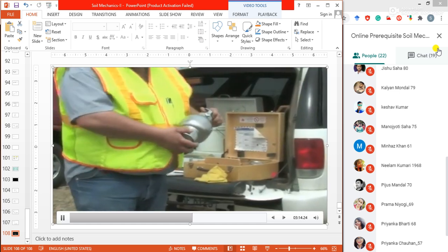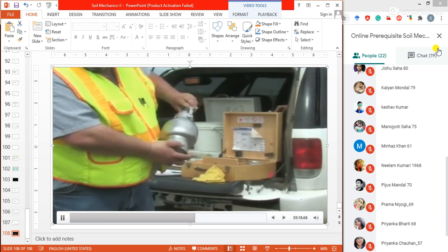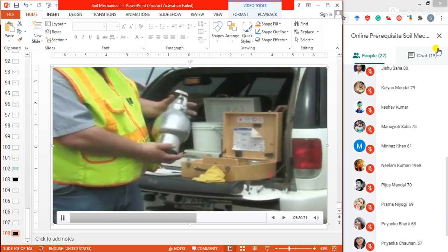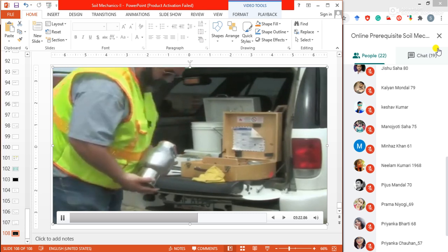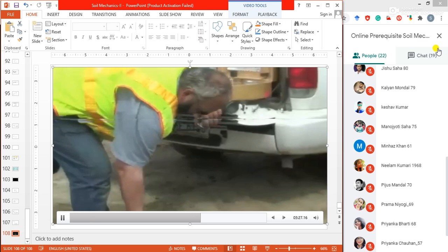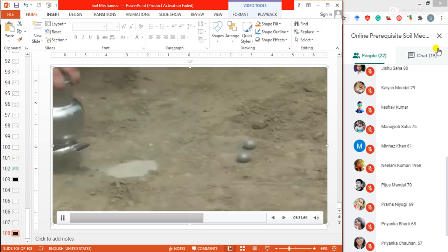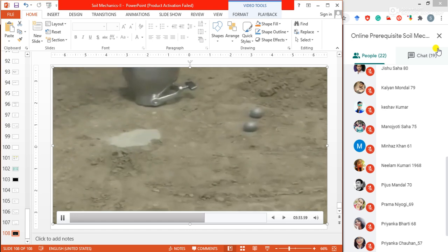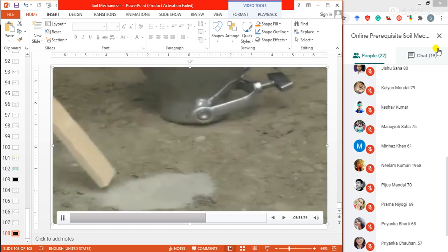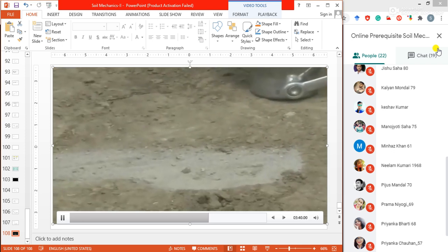At the completion of the test, the moisture tester needs to be opened carefully. Locate the arrow on the flange or lip of the cap and point this downwind and away from you. Remove the top screw slowly to vent the gas. Empty the speedy moisture tester and recover the 2 steel balls. Also examine the contents for lumps. If the material contains lumps, the test should be repeated.